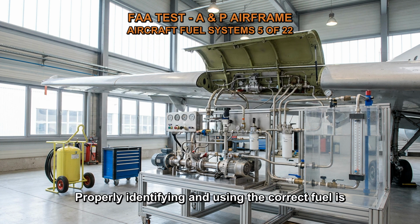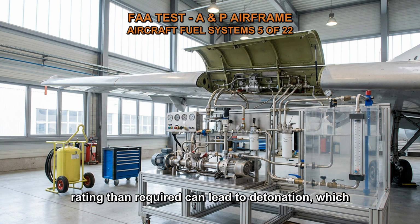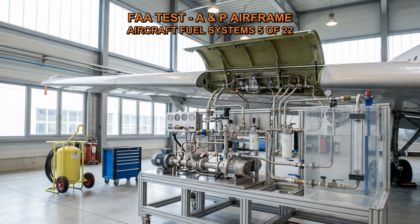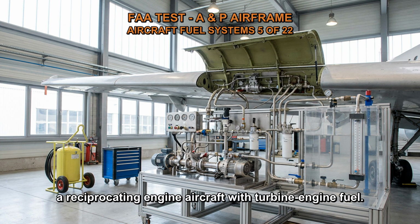Properly identifying and using the correct fuel is crucial in aviation to ensure the safe and efficient operation of the aircraft. Using fuel with a lower octane or performance rating than required can lead to detonation, which can cause significant damage to the engine. One particular concern is the inadvertent fueling of a reciprocating engine aircraft with turbine engine fuel.